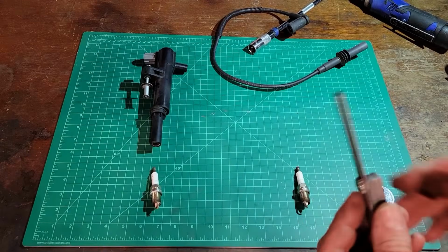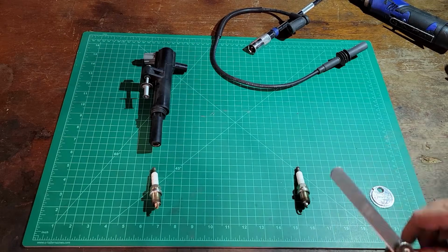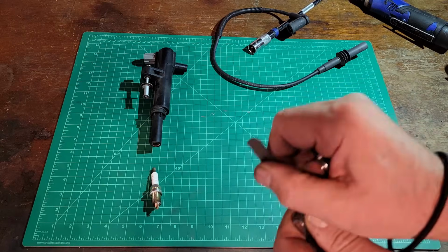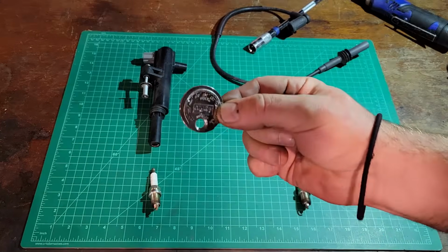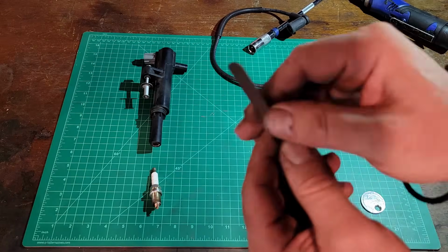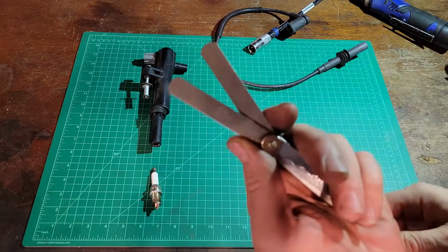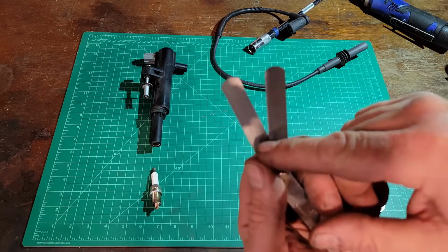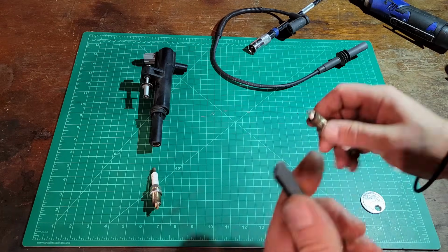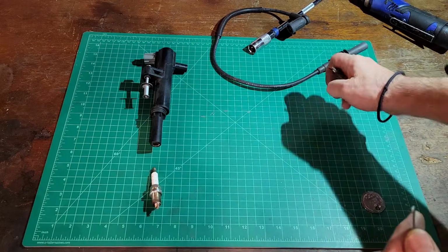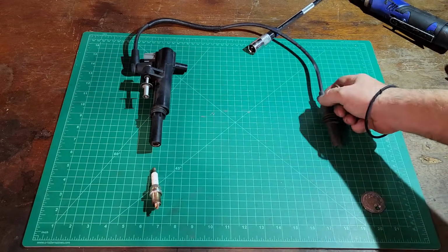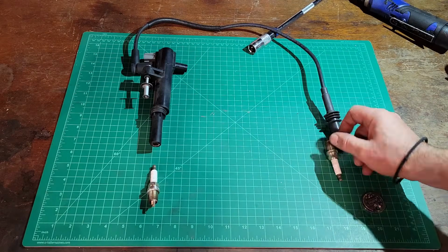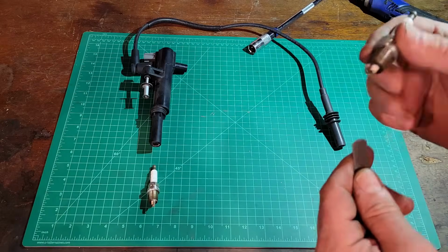All right, the first thing is I set the gap with feeler gauges, but to quickly check what they're at, you're not going to sit there and play with gauges to see what an old plug is. These come in handy for that. But I set it where it's supposed to be. It's 43 thousandths. So whatever you've got to come up with, I have a 35 and an 8. But this would be the one that was firing. I'm keeping track of which end would have been on the exhaust or on the companion cylinder, which end's right underneath the plug. Then I'm going to record everything.